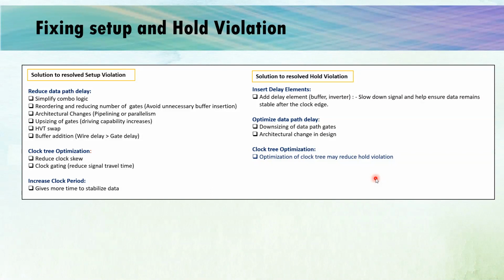Another thing is that in a synchronous digital circuit, where multiple flip-flops have a common clock signal, setup and hold analysis helps ensure that the data transitions occur at the correct time and place, maintaining synchronization across the circuit. It also helps us avoid metastability in our circuit: by telling that setup has failed for a particular flop, the designer can resolve it, ensuring that metastability won't occur in the actual hardware.